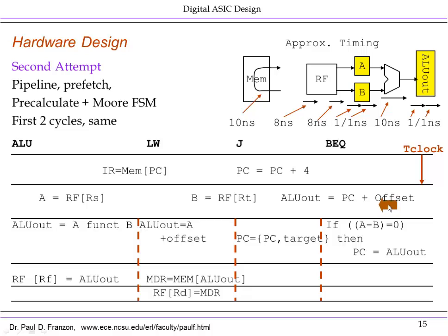And then the question is, can we do something else in this clock cycle since the ALU is not being used? And this is that answer. We're going to calculate the potential branch address earlier than we did in the previous execution stage. This was actually otherwise going to be empty. We're going to take 4 clock cycles to change a branch.